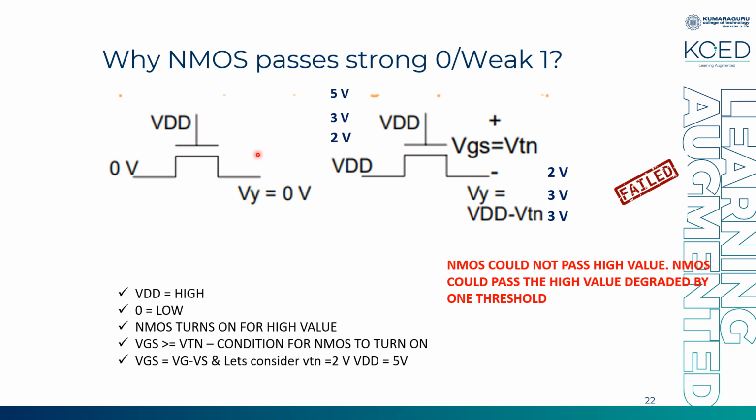Okay, so a pass transistor can conduct in both directions. So if you consider this place as drain and this place as source, this justification would be done exactly the opposite way. Let us see what should I do to sustain or to obtain the condition VDD minus VTN at drain. In that way they would have derived and they would have obtained the condition also.